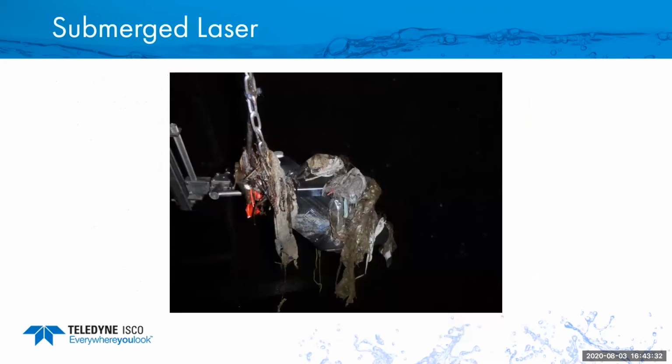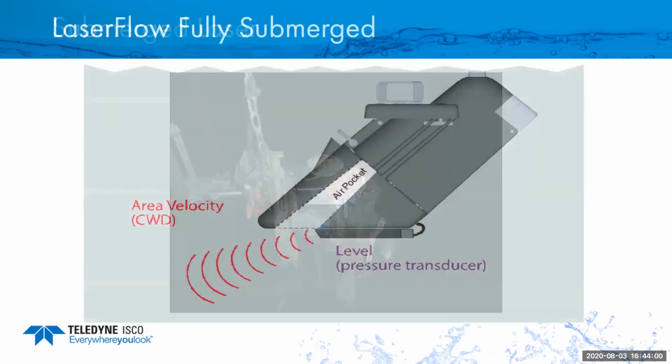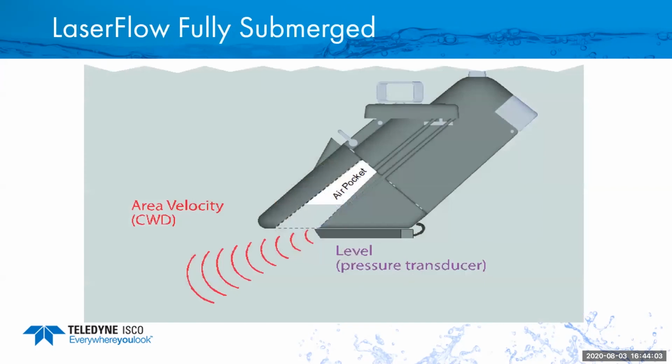Okay, so what happens? We're going to wrap up here in a few minutes, but I wanted to talk about what we do when it goes underwater. This is one that was in Michigan, and the thing gets covered quite often. Anything covering it like that is going to make it difficult to measure, so you may have to clean it off. But the laser is designed for 6 feet submergence, 72 hours. In this case, they had a nice log chain attached to it, so it will not get torn out of there.